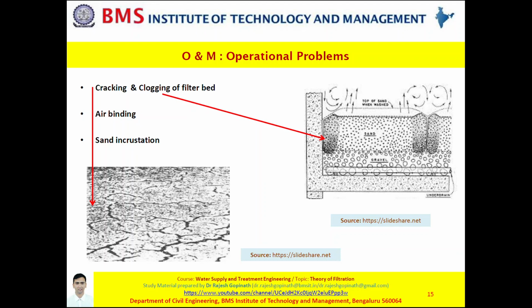For instance, lime. When such heavily limed water enters your filters, there is crystallization of calcium carbonate. As a result, there is more deposition of the sticky flocs and gelatinous materials. This invariably will reduce the space which was available for filtration.